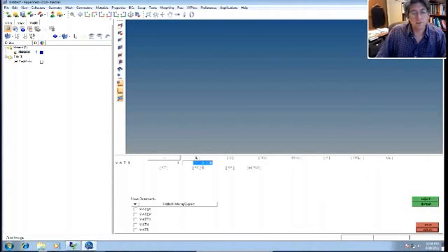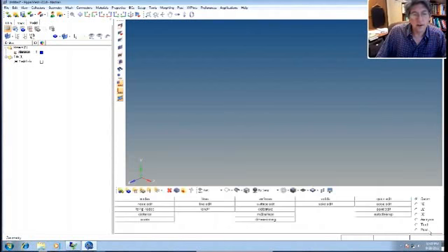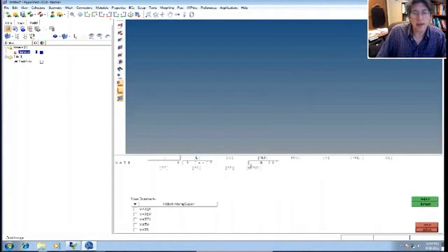So let's make the material. We'll use inches and pounds. So we'll define Young's modulus as 10 to the 6th psi, and we'll put in 0.33 for Poisson's ratio. It's really all I need to do. You can see here you can add additional lines for other optional lines in the Mat 1 card. But that's all we need. So you just hit return. And now it's created. So for example, you can go back later on and edit those if you want to.